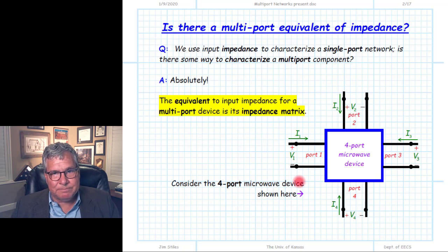It's a sinusoid. What we're saying here by this notation, where we have plus to minus, and where we have current flow, the arrow rather, as pointing into the device, all we're saying here is that when the voltage at this terminal is higher than the voltage at this terminal, then we call that a positive voltage. If the reverse is true, if the voltage at this location with respect to this is higher, then we would call that a negative voltage.